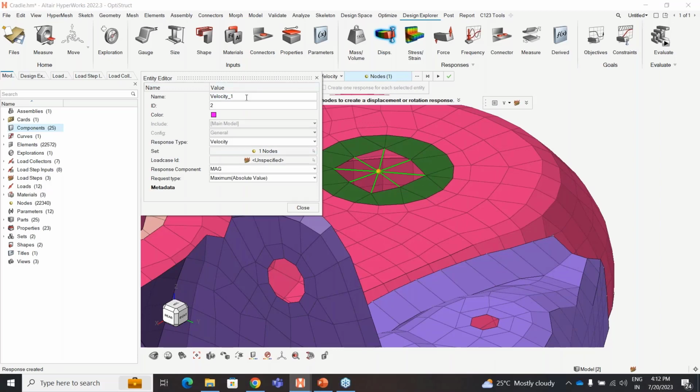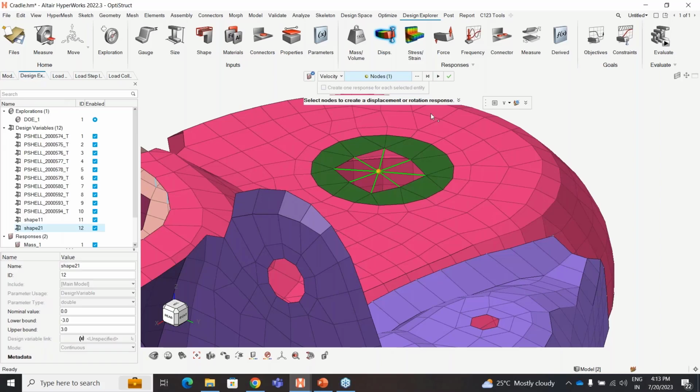So suppose I'm saying velocity underscore torsion load, and then I can choose the load conditions over here. Front torsion, right? I'll say it's front specifically so that I know. And in this case, I'm looking at the response at particularly maximum z direction. And the frequency is something I can specify. In here, it was somewhere around 89, so I'm just saying, okay, till 100. And that's it.